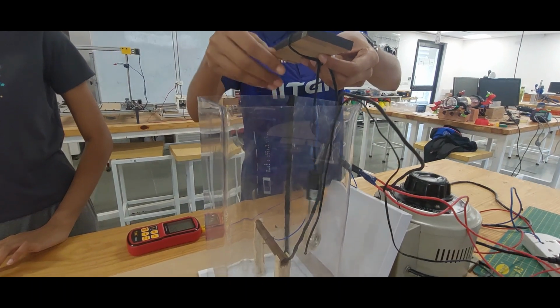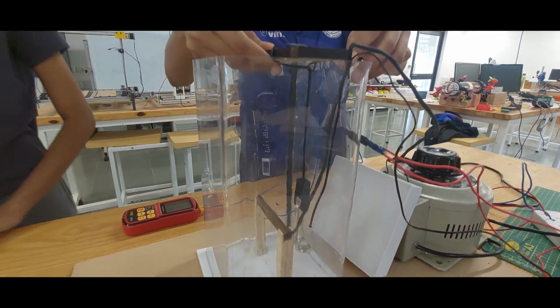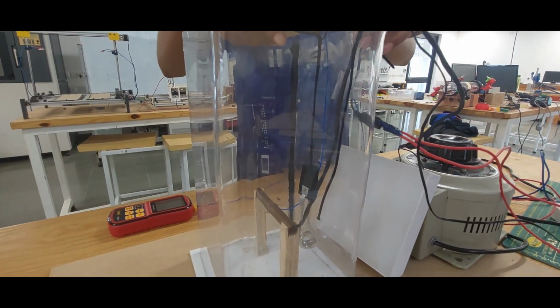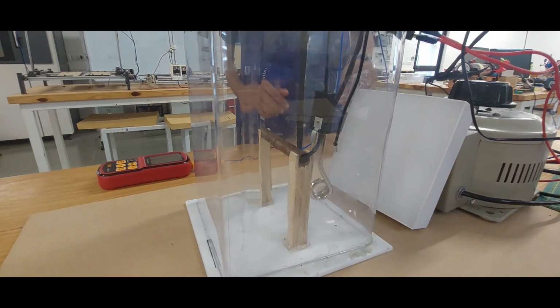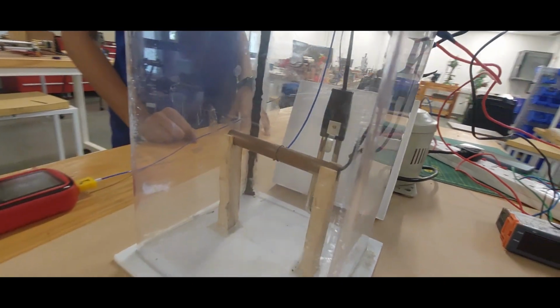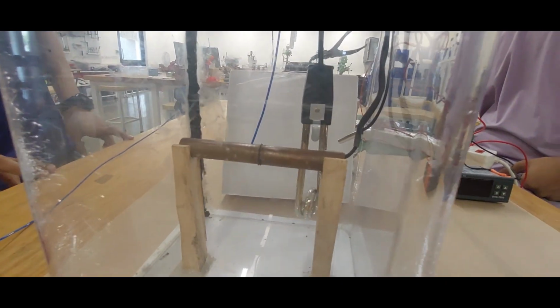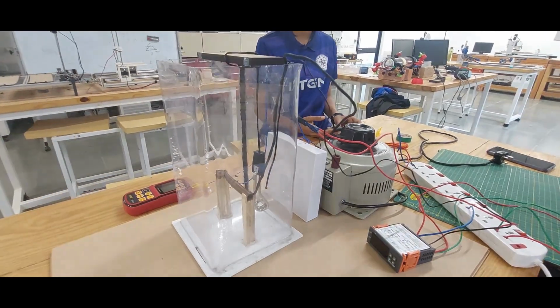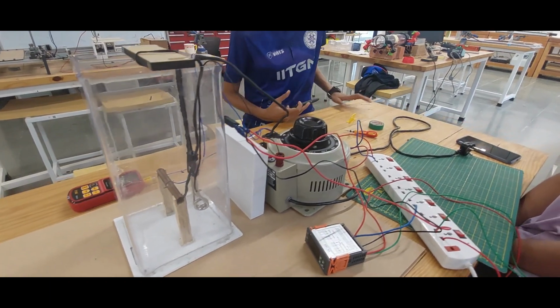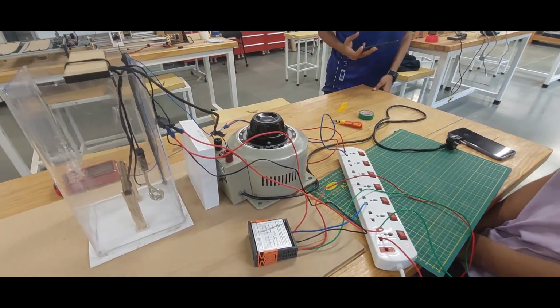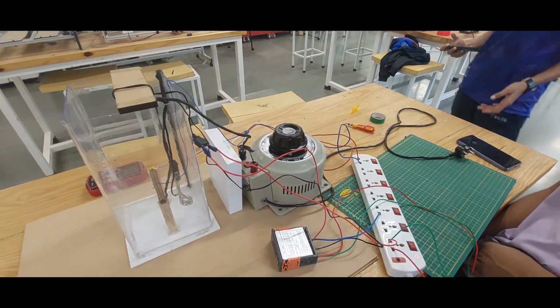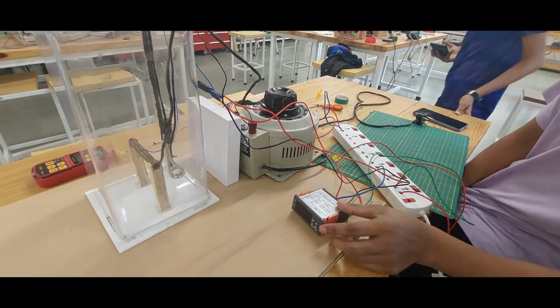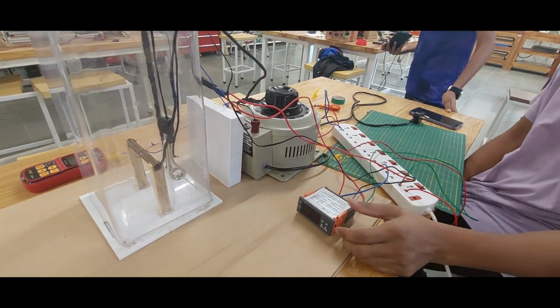An immersion heater is used to heat the water pool in the transparent bath. It is immersed in the water and connected to the temperature controller. The temperature controller helps to maintain the desired water temperature during the experiment and ensures that the water is at the set boiling point. It also regulates the power supplied to the immersion heater. By monitoring the water temperature using a thermocouple, the controller can adjust the heating element's output to achieve and maintain the desired temperature for the boiling experiment.